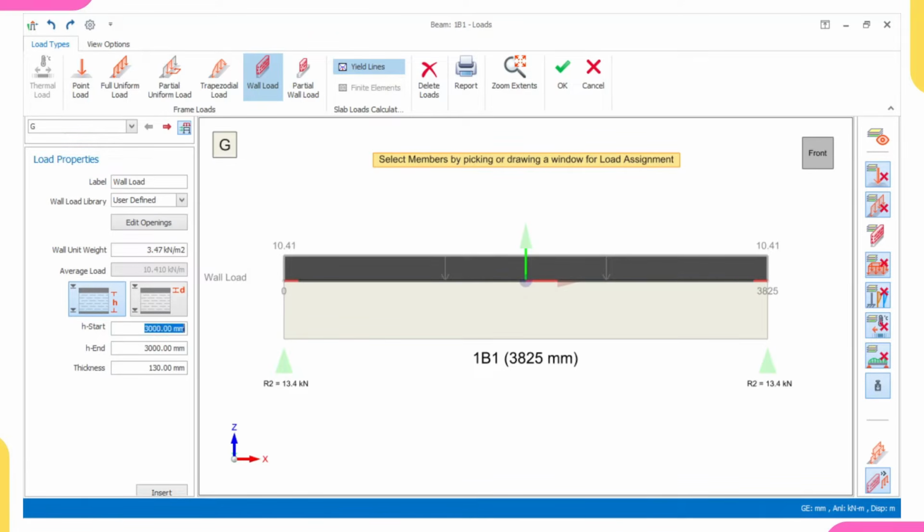So if you do it, you'll be having 2,700, since this is in millimeter. I hope you understand. Look at it. This H is from our slab to where our beam stopped, and our story height is 3 meters. So if you do 3 meters minus your beam depth, you now be having 2,700. So let's click on this one. If you see, that's our drop down beam, this D. Our drop down beam is 300, while the remaining part from drop down beam to the floor is 2,700. So if you do 2,700 plus 300, you be having 3,000.